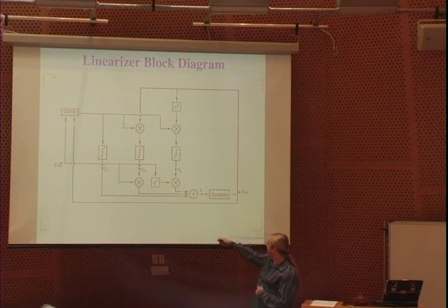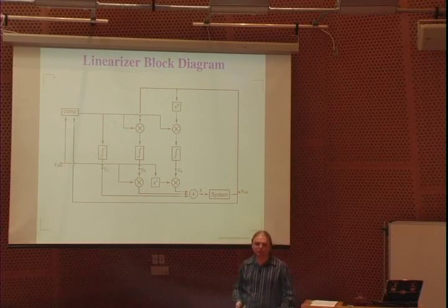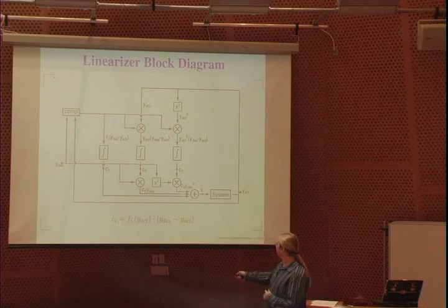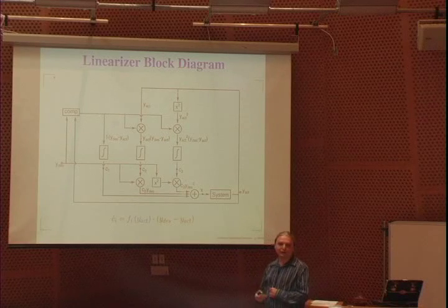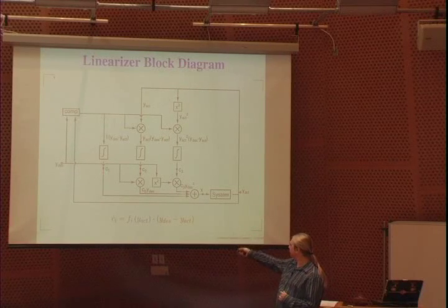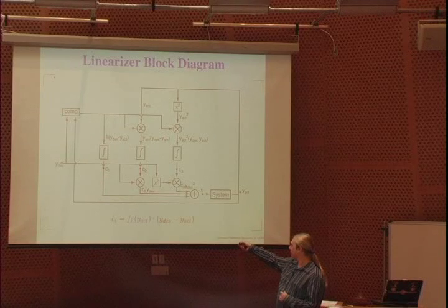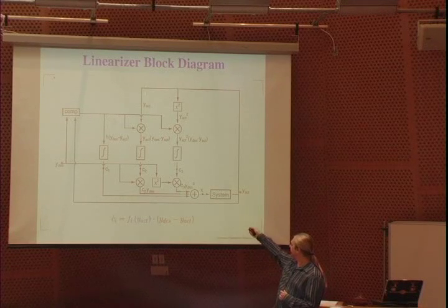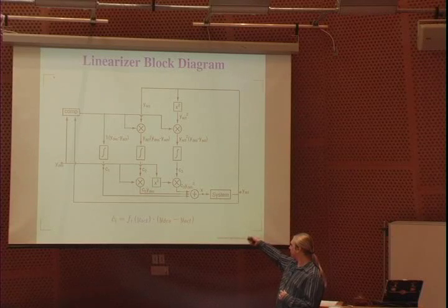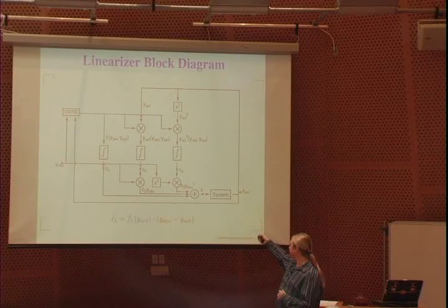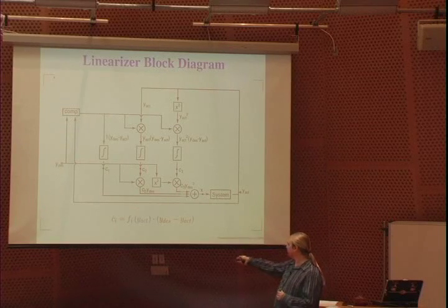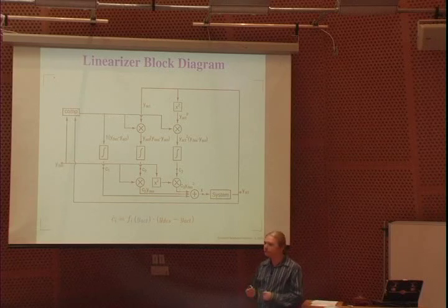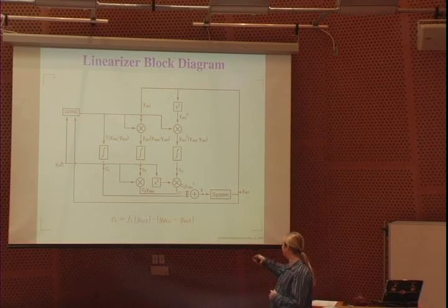So if we build a system to do this, this is the block diagram of it. It's pretty simple. What it's doing here is that comparator is calculating the desired value of y minus the actual value of y. This is integrating to get C1, y1 times the desired value of y minus the actual value of y. This is integrating the actual value of y times y desired minus y actual. This is integrating y actual squared times y desired minus y actual, so that's how you're computing that. And this is just a feed-forward calculation of playing the model through to try the system.